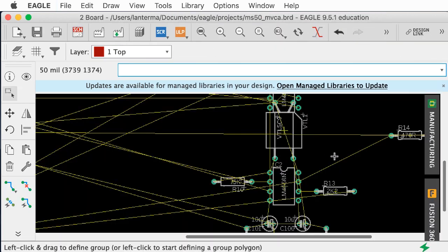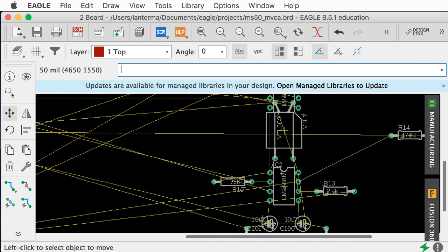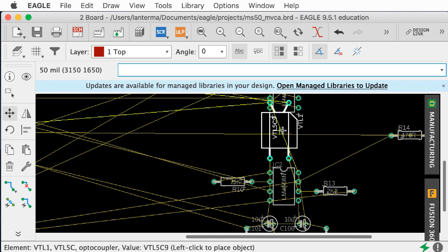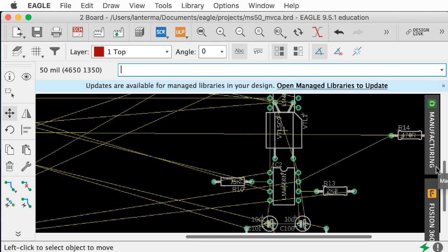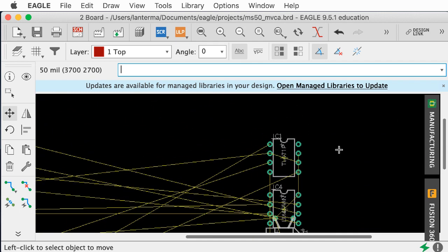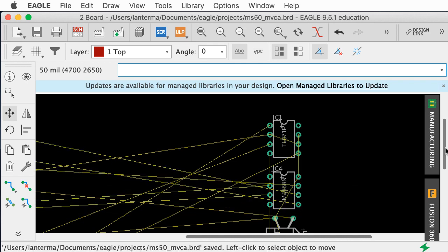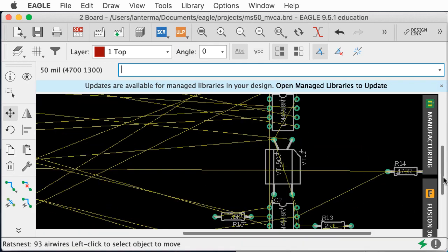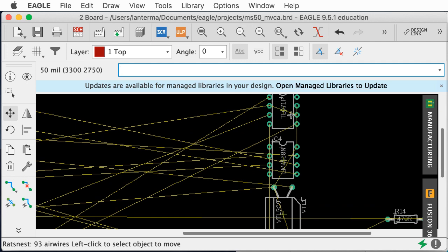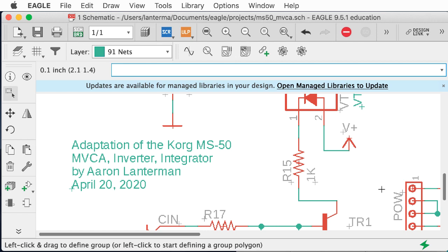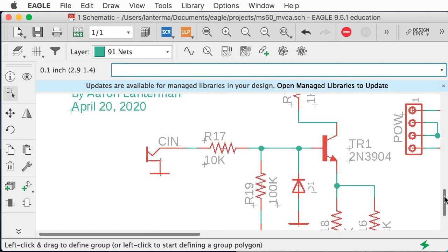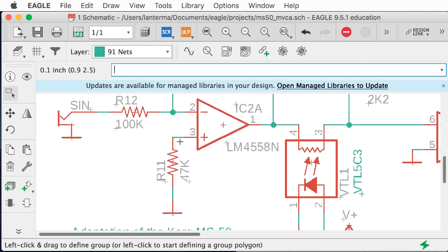And now if I go back to the board and I type rat's nest, now I've got a nice structure here in terms of what's hooked to one on each side. That's kind of pleasant. To make room, I will move the op amps for the other circuitry up a little bit. Now that I have that Vactrol somewhere I like it, let me do some work on some low-hanging fruit here. Let's work on the other op amps here. Oh, wait a minute. This one here is low-hanging fruit.